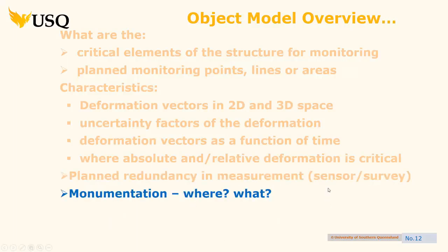And critically, and we'll have some pressure on this, is monumentation. When you build that highway, and you're doing the surveying for it, it might take a year, right? By the time you go from the beginning to end, you might put some things deep driven into the ground, some recovery marks, because you might have to come back if a bulldozer drives over it or whatever, right? When you're doing a lot of monitoring, you're saying someone in 50 years' time, they don't even attend lectures.